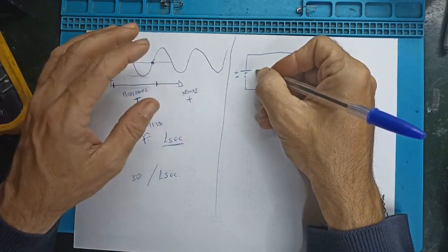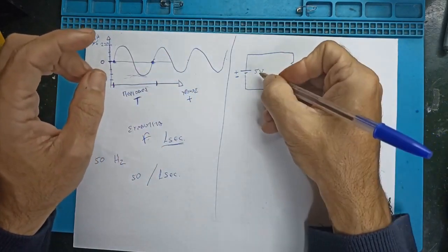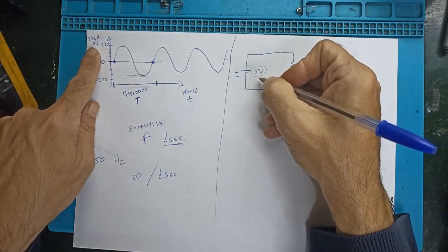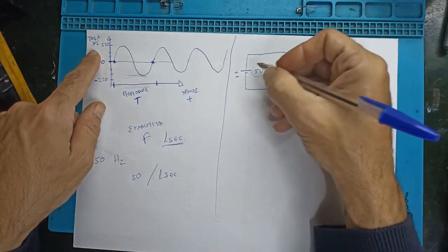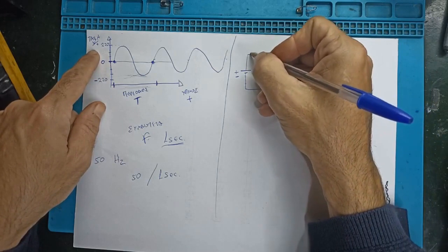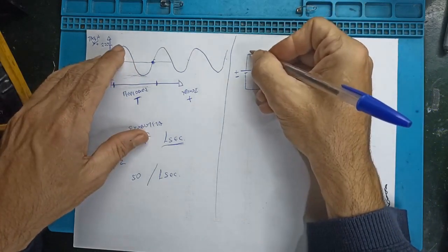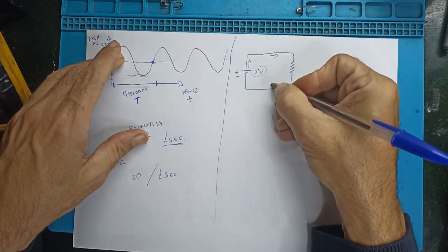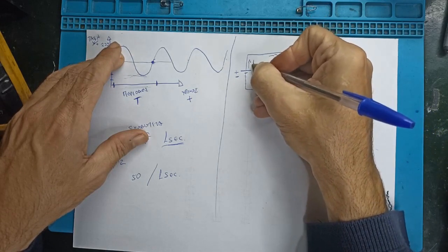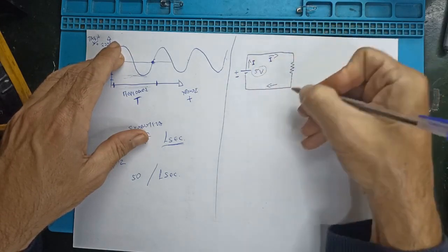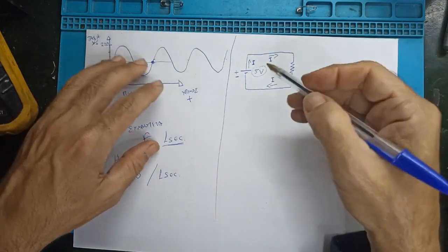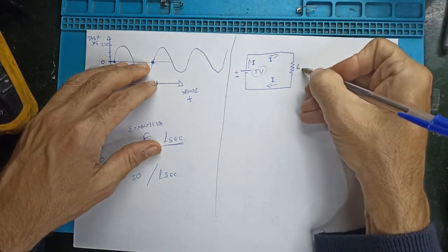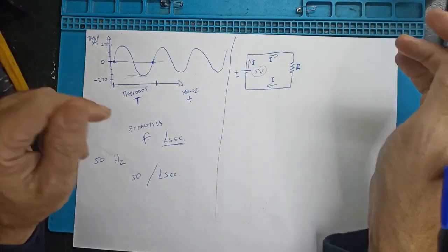So I understand that the voltage will remain stable at 5 volts, while the current will pass according to the resistance we will have put here. The current intensity, in other words, is not constant. If I have a 5-volt 10-amp battery, it implies that whatever circuit I create, I will pass 10A through it. The 5 volts will be standard, but the current will be determined by the load we provide to the battery. For example, if our load is a resistance, the smaller the resistance, the more current will pass through the circuit. As the resistance increases, the current decreases.